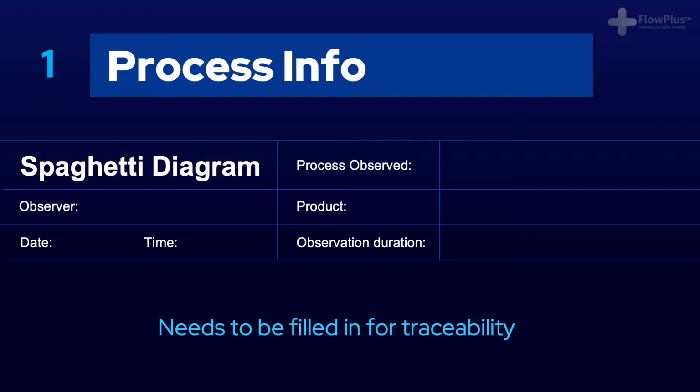The observation time should be recorded once the observation has been completed. In terms of how long to observe, I would suggest watching at least one cycle of the workstation as a minimum wherever possible. However, this may vary depending on the nature and duration of each cycle. Typically, 30 minutes observation time is long enough to paint the picture required for each workstation or process.